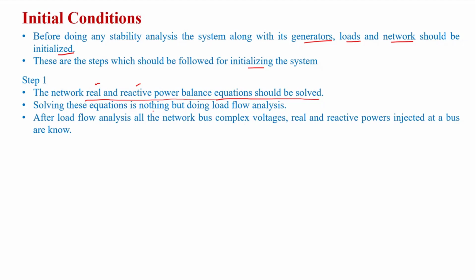Then how can we solve this? If we have a small network, like a 2-bus network, we can directly solve it. But if we have a huge network, then we need to solve it using load flow analysis, right? So we require load flow analysis, which is in fact very essential. Load flow analysis is generally used for steady state analysis, but here we require it just to initialize the parameters. Solving these real and reactive power balance equations is nothing but doing the load flow analysis, right?